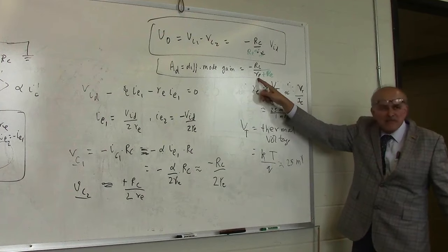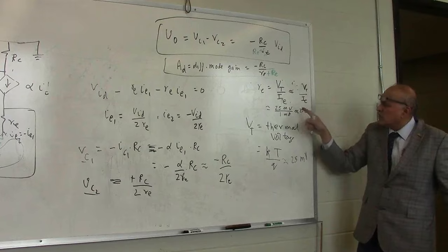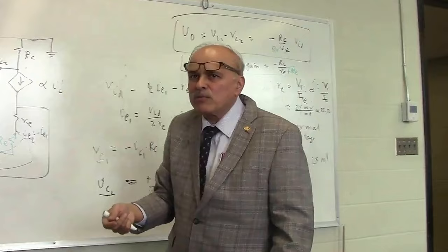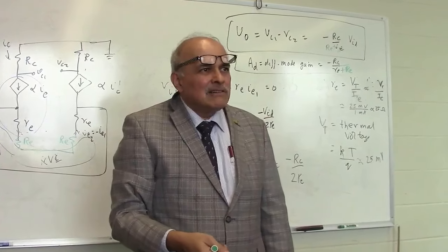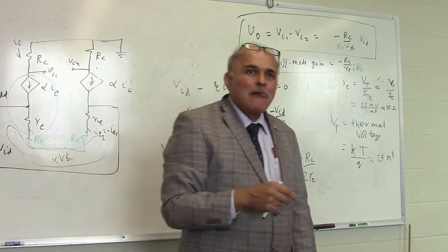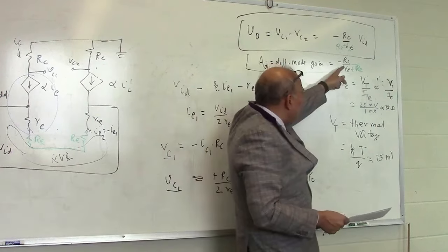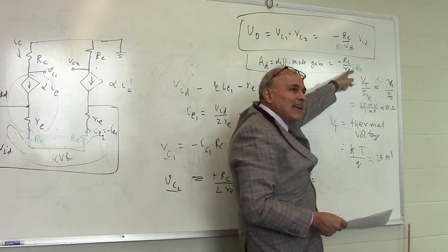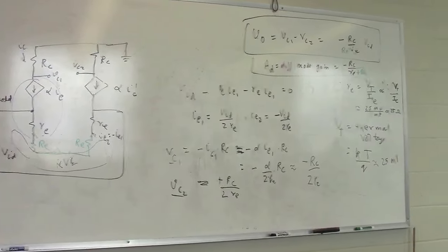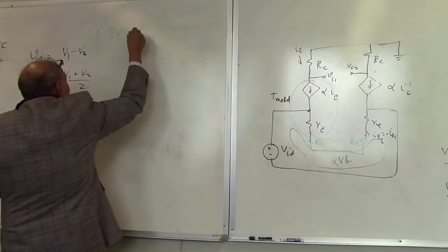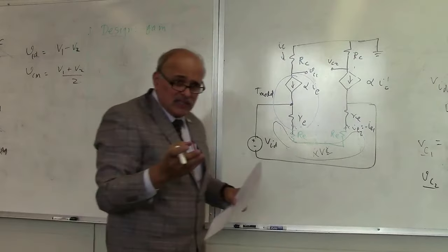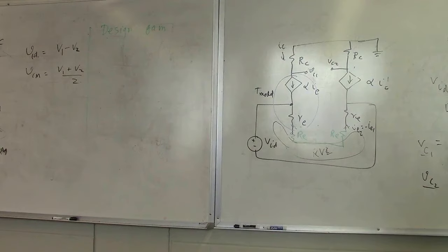So now if this is approximately 25 ohms, we use a resistance much bigger than 25 ohms. What's a resistor much bigger than 25 ohms? What about a billion K? Well, of course you have to use your judgment how big you want it, because you want a gain of RC over RE to be, as your book says, in your design, a gain of, what is the number here? Can somebody read from the sheet? 25 to 37. 25 to 27.